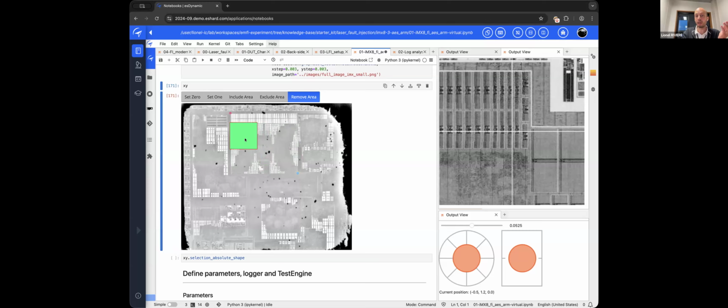Which one is the right one? I don't know. So at the beginning, when I did the experiment, I scanned everything. Turns out after the experiments, my code was only triggering core 0 because I was working at the bare metal level. Multi-processing was not active in my firmware. So I can focus here on core 0.